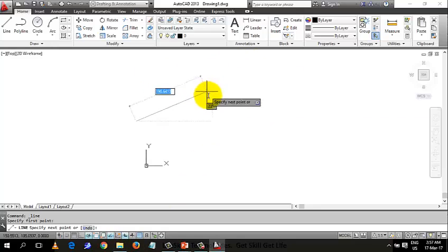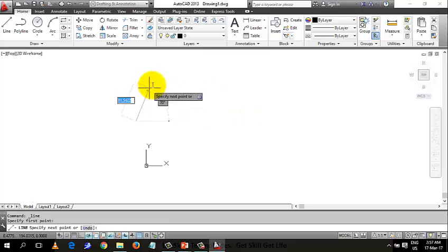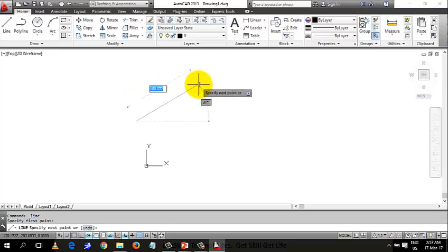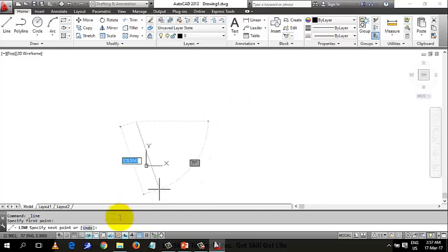But if you turn on dynamic input, you are going to see those text boxes, and they allow you to quickly see the angle at which you are drawing a line and the length of the line. So the command is being shown. It's a cool thing if you are already comfortable with AutoCAD. But for now, let's disable it. So don't forget that the polar tracking, the object snap, and the object snap tracking, I recommend those three to be enabled. So now back to our absolute coordinate.